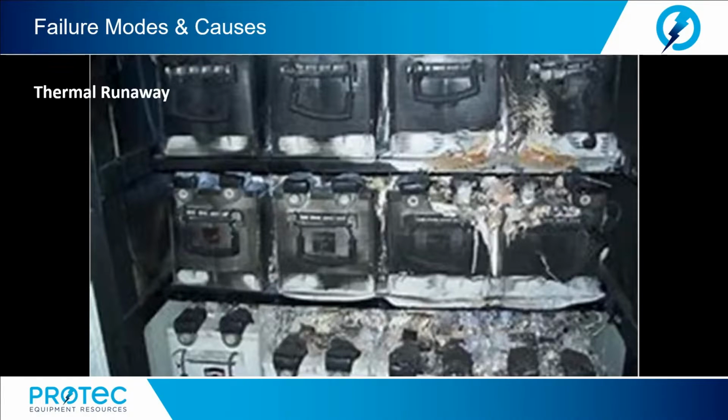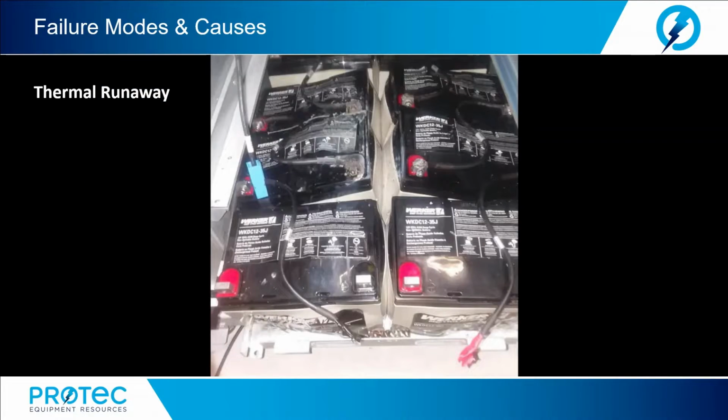All right, thermal runaway. Thermal runaway is a condition that occurs in a battery, especially valve-regulated types, when charging energy results in heat generation within the battery greater than the heat dissipated, causing an uncontrolled rise in battery temperature. This can cause failure through cell dryout, shortened life, and or melting of the battery. Once started, thermal runaway is self-sustaining. It can end in complete and catastrophic failure.